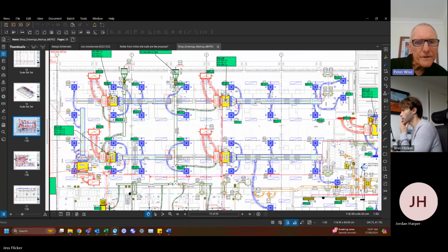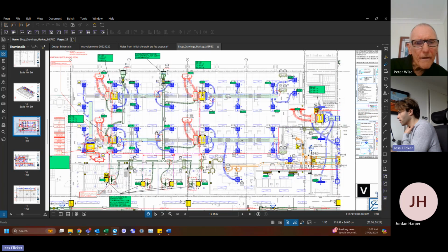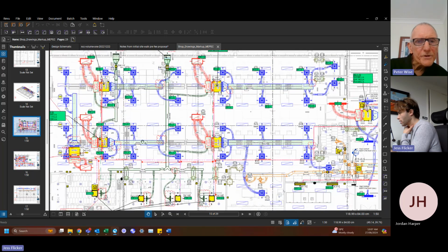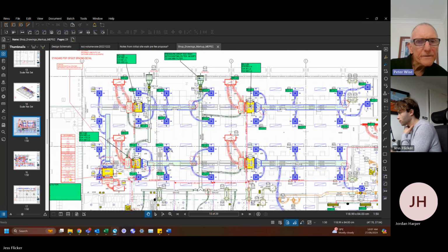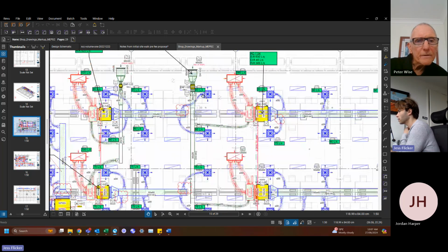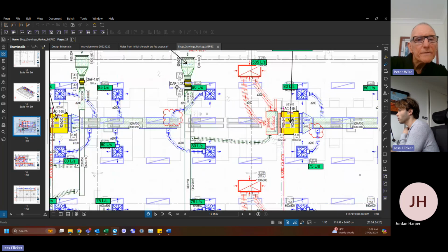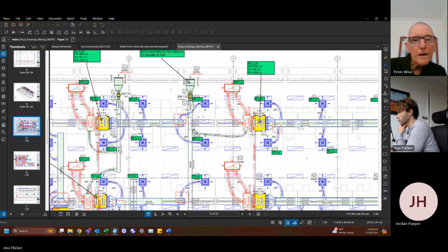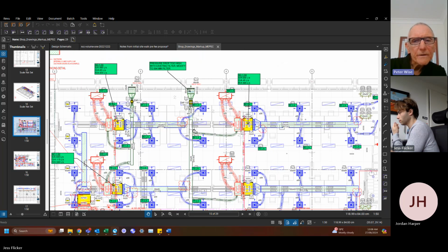So what have we got there? I think this is the space I was thinking of. I think they actually don't precondition the outdoor air. They've just got a fan that pulls it in from outside. Right. So what's the flow rate of the outside air there? On the fan there, I noticed if you go up to 80. Oh, it's only 80 litres a second. Oh, yeah, sorry, so no, 180. So 80 is the diffuser and 180. And this is in Melbourne? It's in Brisbane. Oh, okay. So that's a different climate zone.